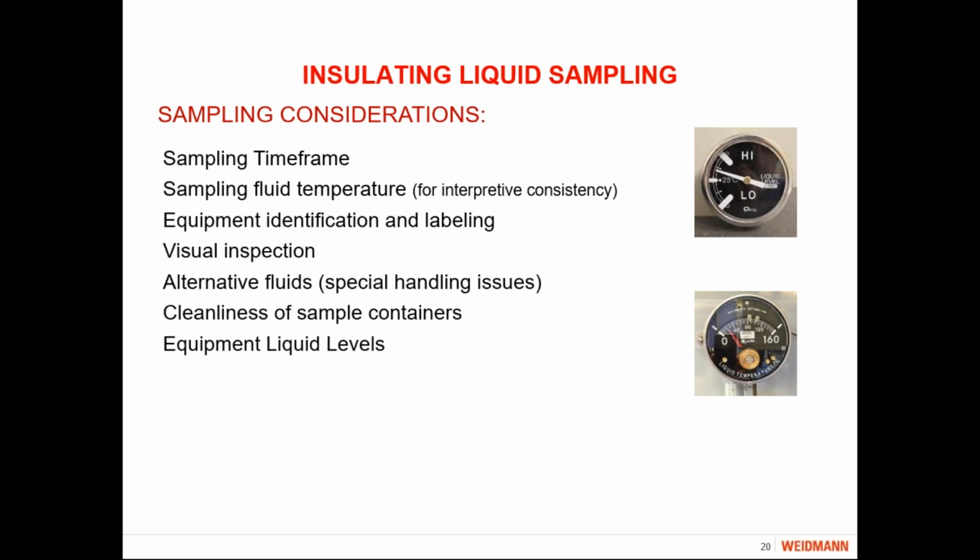When you do take the sample, do make an effort to determine what the temperature of the oil sample was as it was taken, and record that on your sample form so that we can include it in the information on the test report. It's not absolutely critical to know, but in some cases, if we can see a wide variation in oil temperatures, that can sometimes explain why a normal transformer looks like it's generating active gassing patterns. It could just be because as the temperature goes up, it drives more gas out of the oil. So do identify the temperature if you can.